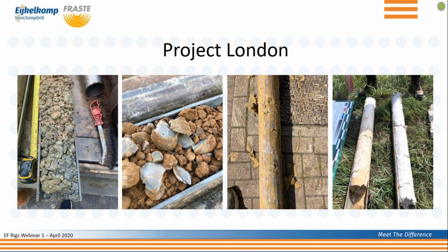Well, cable percussive will punch the holes out, and then you'll pick it up out of a bucket and put it in a pot, and that'll be a very good guess close to the depth of that sample. With Sonic, you're getting exactly what it says at that depth, and you can prove it and back it up. Rotary, unless it's in the right grounds, they won't get recovery. In the right ground, yes, they will have recovery, they can tell you what's there, and they will get you a good liner of the stuff. But if it's gravels or sands, you've got no chance.